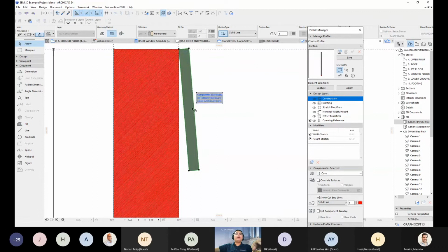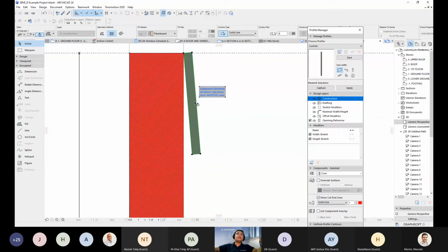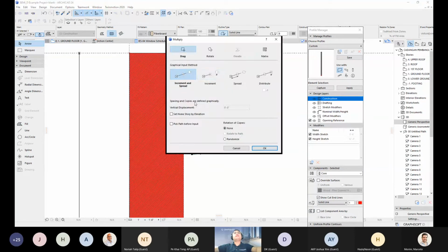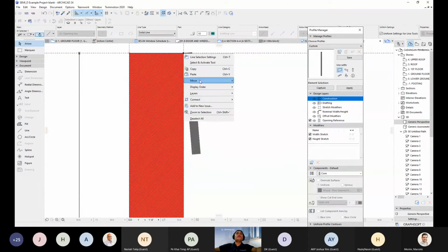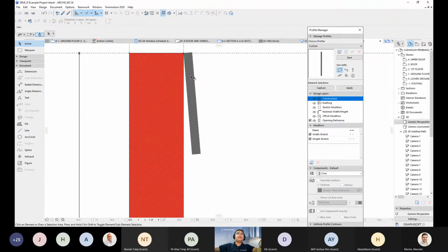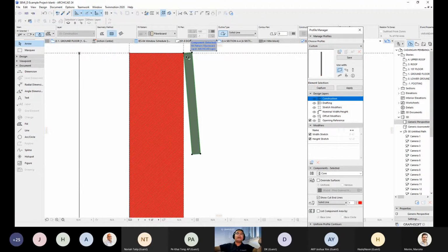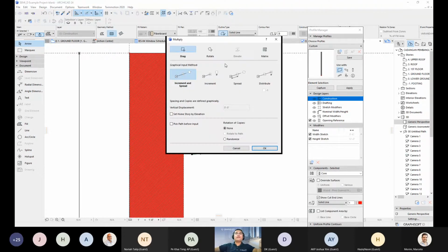After that, what I want to do is use multiply. So I just use Control with the multiply. Or you can just right click, move, then go to multiply, drag a copy, shift drag a copy. But I want to use multiply, just select this fill and then go. I want to split because the height of my wall is 12 feet, right?